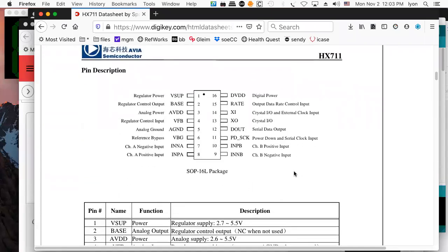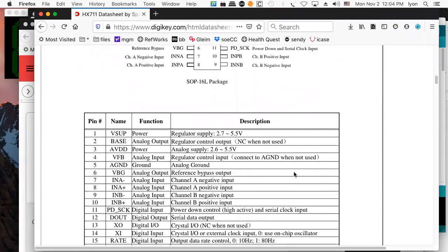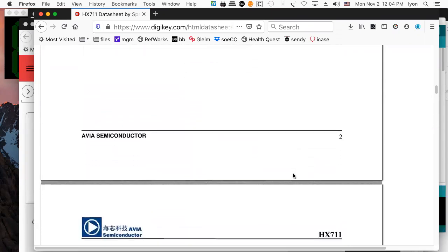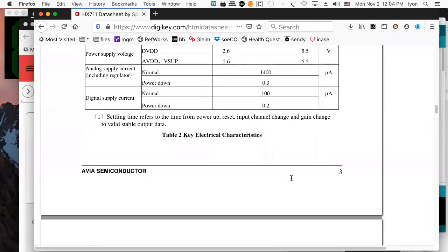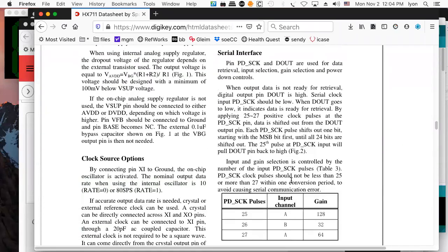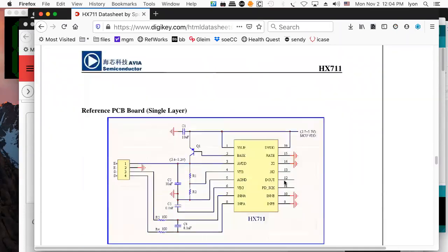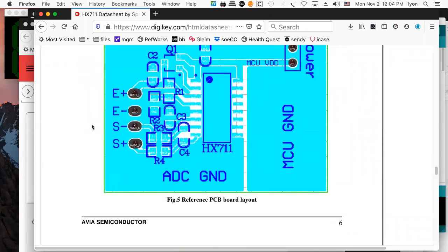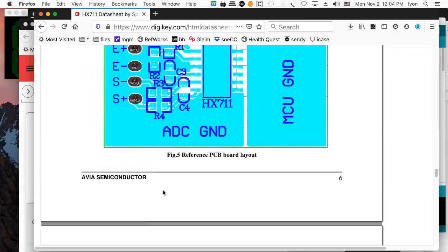This also has an interesting interface going through the analog inputs of the Arduino. And so that's a feature that requires that you have reasonably good signal and precision. Let's see now. What else do we need to know? I think that's about it. So you're going to end up, these little guys over in here are your analog inputs, and they're going to be hooked to the strain gauges, which will be mounted to load cells.